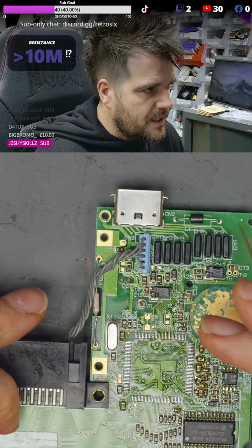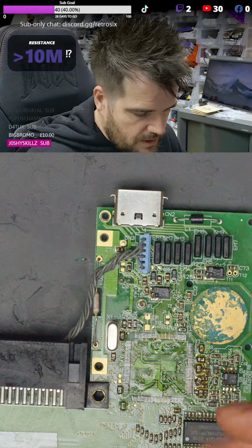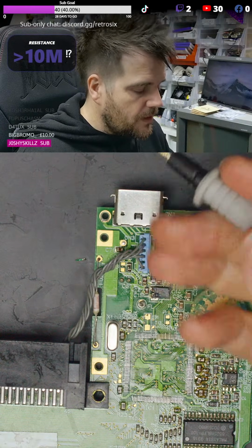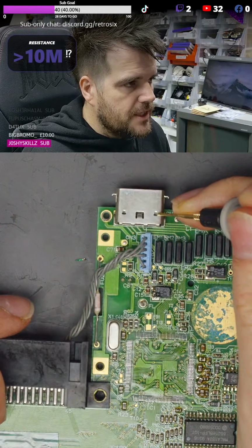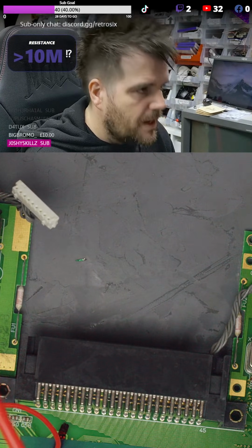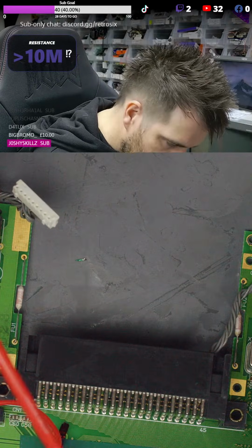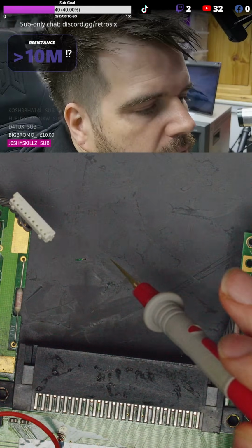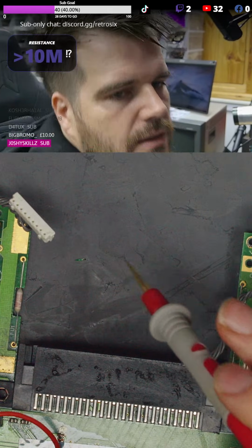One idea is, because we've got a short to ground, we can go around with your probes in resistance mode, probe on, say, a ground point here, probe on the 5 volt over here with no power applied. That's the important step. Put the probe back in and go onto here.